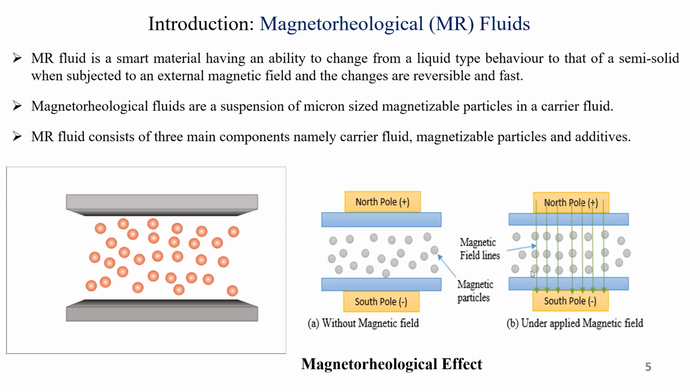So if the rotor and the stator is filled with the magnetic fluid, and if this field is applied, and this becomes solid and these two will not move, then the brake is applied. Or if I don't apply the magnetic field, and these are free to move, then this moves and this also moves as an integral part.